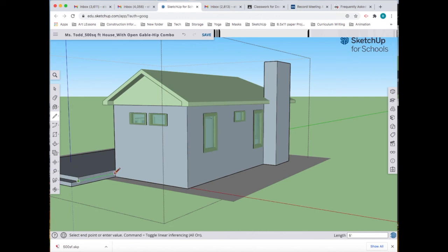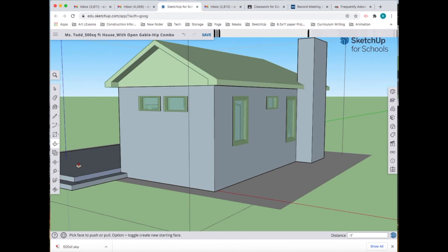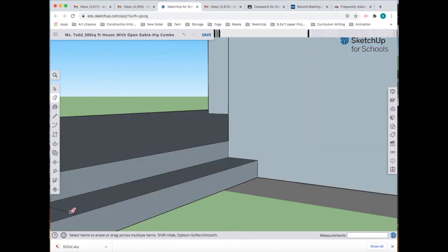All right, I'm going to snap on the green axis here into the corner and use that push-pull tool to bring this out. And maybe I do it 1 foot also. I'm going to put the hot tub right there on the ground. I think I'm going to make an area where there might be pebbles or something. And I'm just going to delete that line.